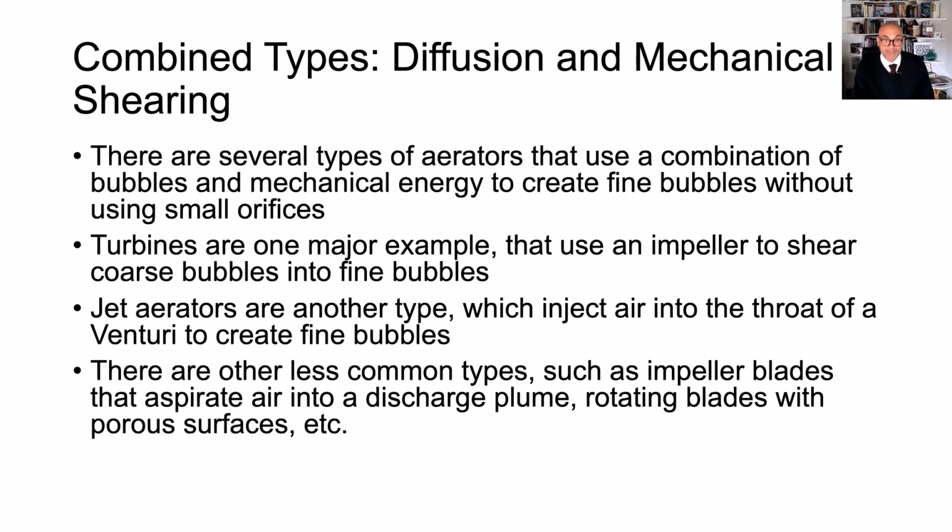And so some companies have marketed hybrid mechanical systems, so a turbine that mixes the water instead of drafting water in or splashing the droplets out. It will push the water in front of a coarse bubble diffuser, so the bubbles get sheared to be smaller. You have now two things: the blower and the motor for the turbine. So you have two mechanical units. The total power is the combined power of the two.